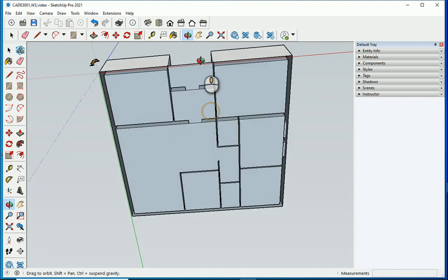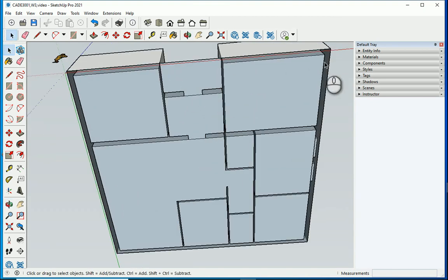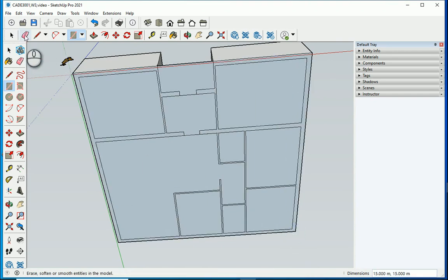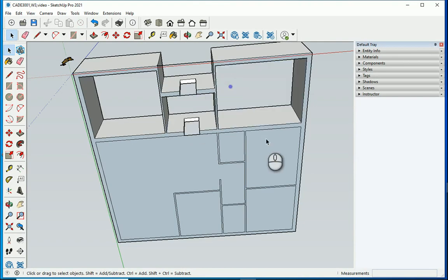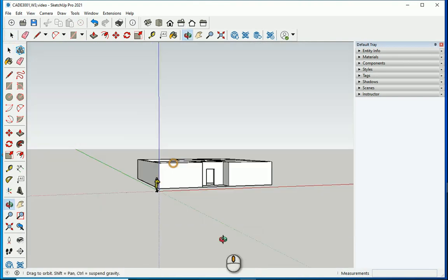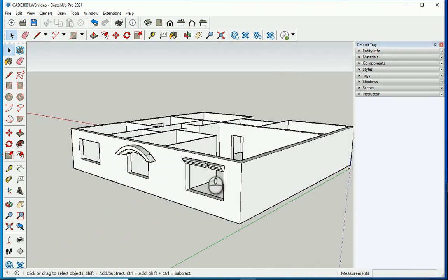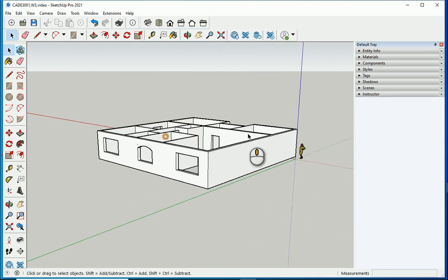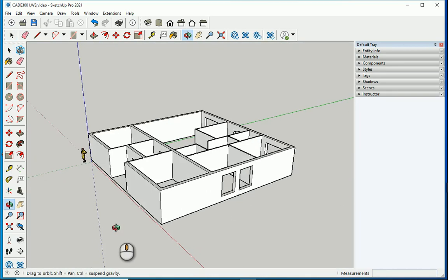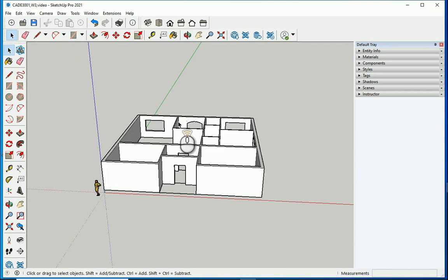And here at the bottom, you see the walls are not capped, so I want to go with one rectangle using R for the shortcut, going from there over there. Now I want to delete these parts in between, so only the walls are left with the caps. I can also hide these two other groups, this one and this one. Now we have only the walls which are capped at the bottom and at the top, and where we have the windows and everything, right?